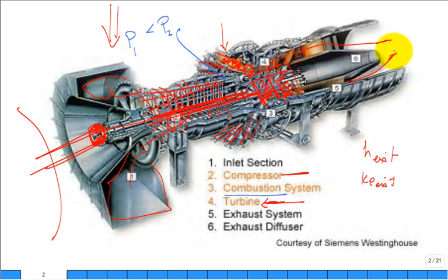Now, when we talk about the gas jet engine, they strap underneath the wing of an aircraft, not this lecture, next lecture, or maybe the following lecture, we'll have a compressor, combustor, turbines, but we will only extract as much energy out to drive the compressor. And the rest of that energy you convert in a nozzle so it goes out as high kinetic energy as possible, as high a velocity as possible out the back of that jet engine. Hence, you get a large thrust. And it's going to push the aircraft down the runway and up into the air, into the sky.